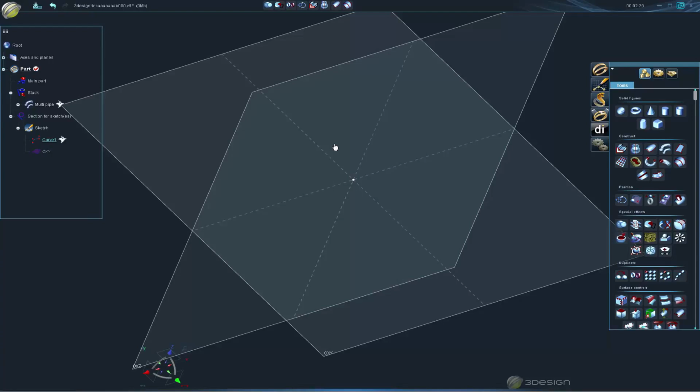Okay. So far with booleans on twist, I haven't had too many issues. The mirroring of the twist can be problematic because of the coplanar surfaces. I did have some issues trying to get those to boolean together. So you will have to, like most Boolean issues, adjust them so they overlap nicely, play around with it to get the Booleans. They are very complex shapes, so you do have some of those similar issues.